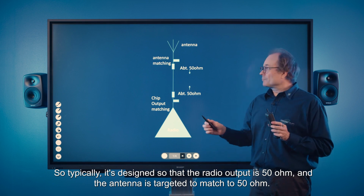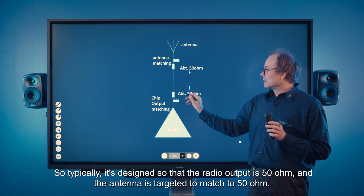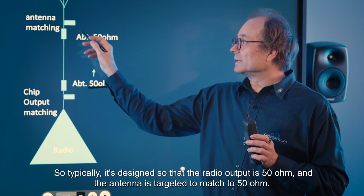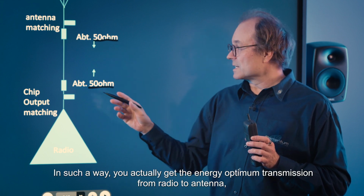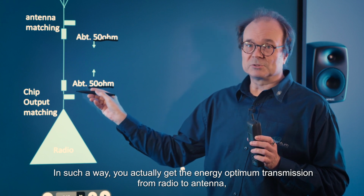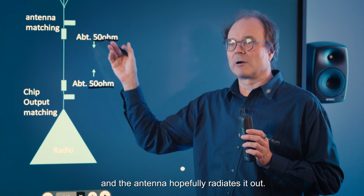Typically it's designed so that the radio output is 50 ohm and the antenna is targeted to match to 50 ohm. In such a way you actually get the energy optimum transmission from radio to antenna, and the antenna hopefully radiates it out.